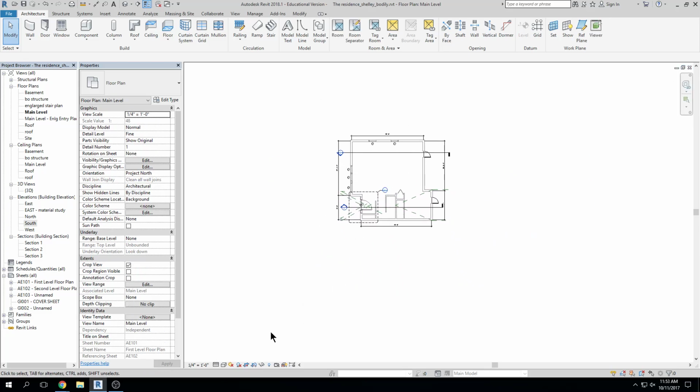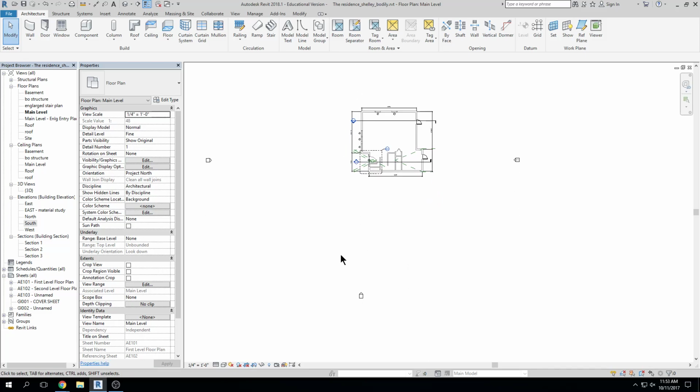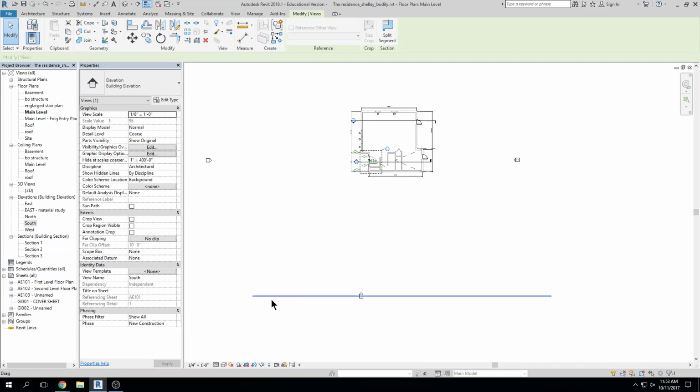I've got this elevation marker out here, and I kind of have a line that says, hey, I'm a certain distance from the house, right? And I can view it from here, and I can view it from there, right? But Revit is basically saying, when it asks me to establish a reference plane or a work plane, hey, where in this depth do you want that to start, right? So it's an easy thing to think about, but kind of a pain in the neck to have to establish when you're trying to create it.